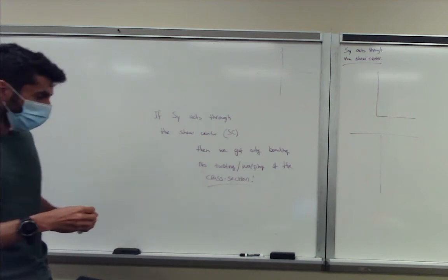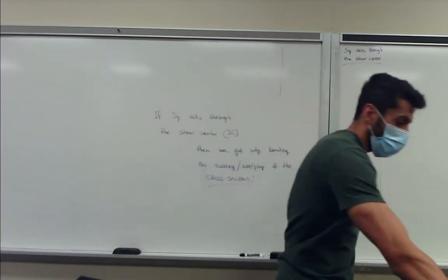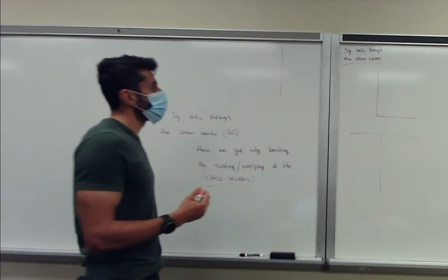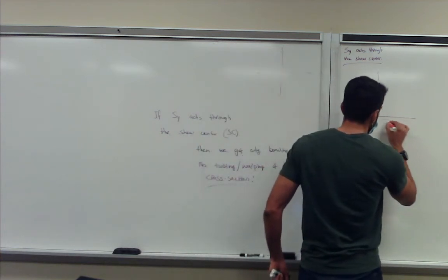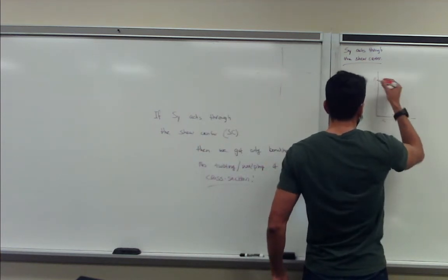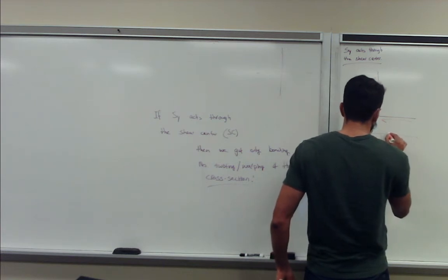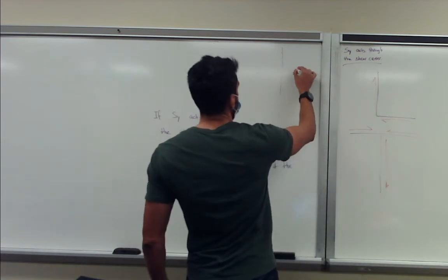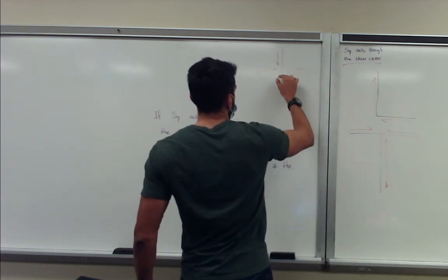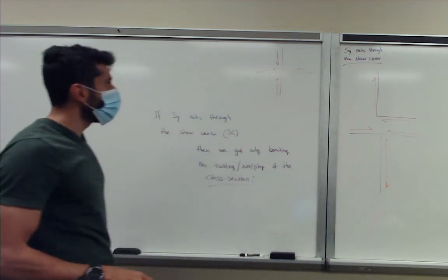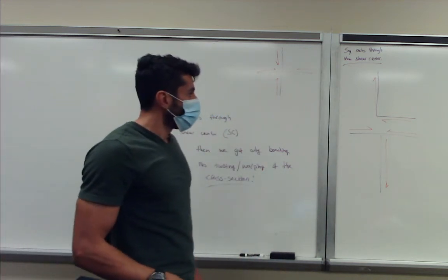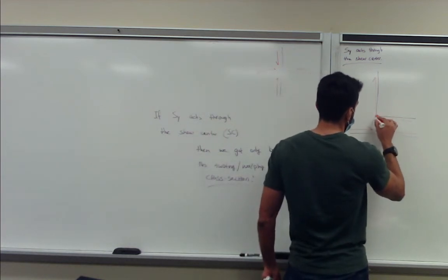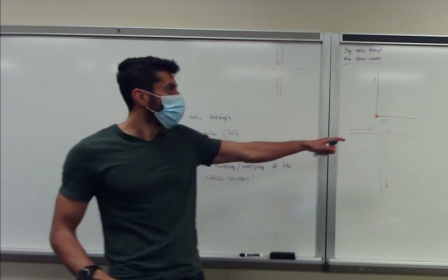If we were given a shear force and calculated the shear flows, the shear flow is going to move something like this, going up and then down, going like this. And this one will be something like this. So we notice that all the shear flows go to this point. So by definition, that will be our shear center.